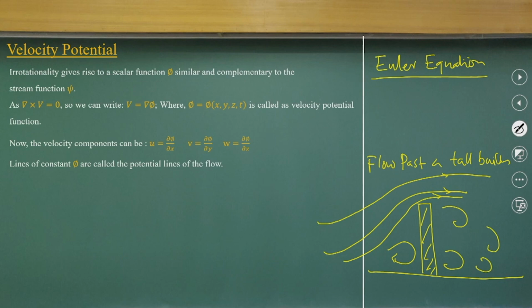If you exclude the region near the structures, the flow outside of the structures is more or less described by the Euler equation. But near the structures, as vorticity, turbulent behavior and flow separations are there, the Euler equation is not valid for this external flow.